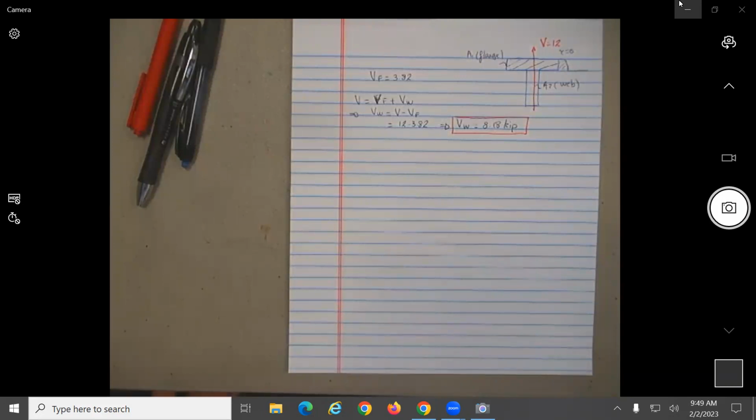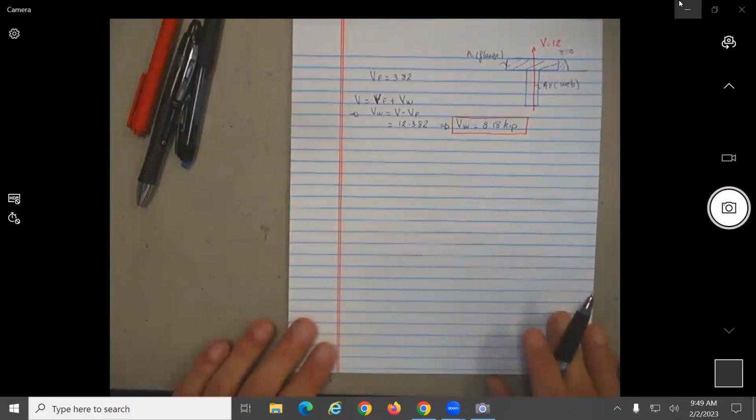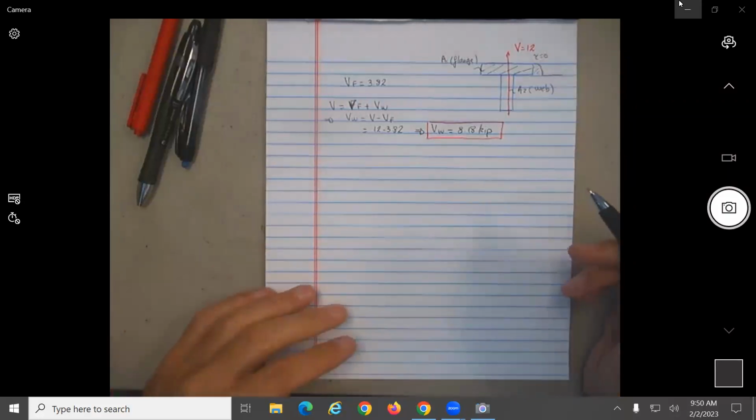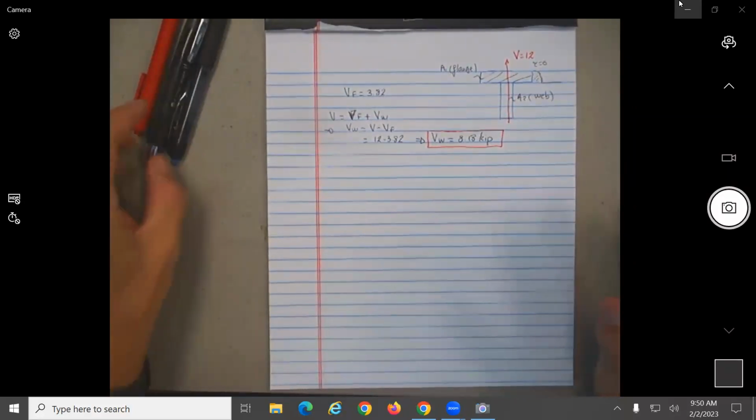Okay. However, shears are very important in order to do what? So, for example, if you want to put on top of a beam some type of plate, and you need to bolt it, how are you going to design the diameter of the bolt that you need to put, or rivets, let's say, and what should be the spacing? If you have a beam and you put a plate on top, and they come apart, it would be due to what? It would be due to shear, no? Because, remember, without shear it is two surfaces in contact, no? All right. So basically, what's important with shear is for something that is generally called, in the textbook, built-up members.